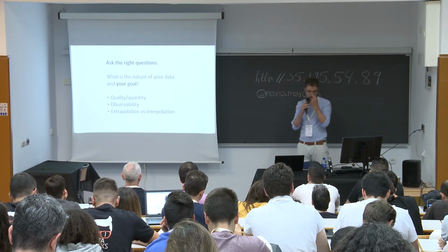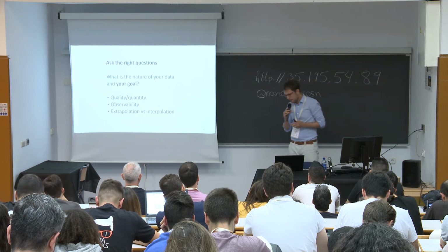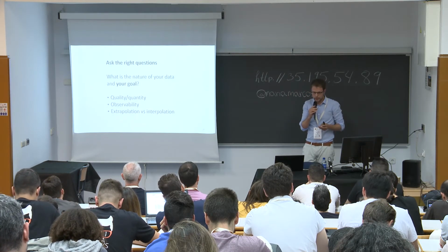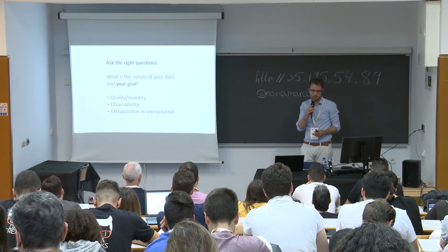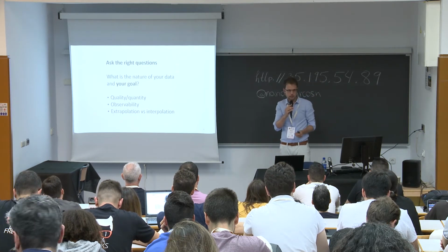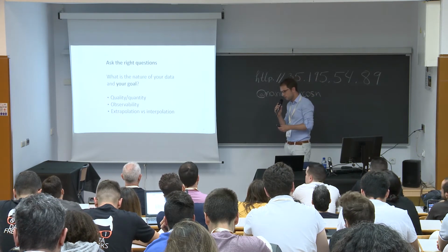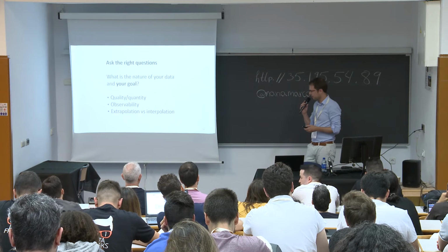Observability, another issue. We cannot measure everything. We measure near the surface of the pipe. We cannot measure the temperature inside because maybe the sensor will be damaged. So it's always good to think about what is the observability of your model.